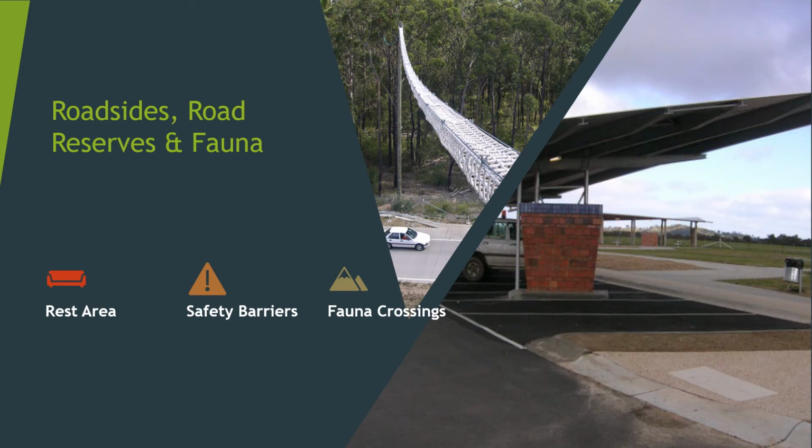Also in this section, safety barriers is discussed, so there'll be 3 areas requiring safety barriers, which is the approach to the embankment, along the embankment itself, and also over the creek crossing. I've chosen to go with steel W-beam style safety barriers on the approach to the embankment and across the culvert crossing itself.